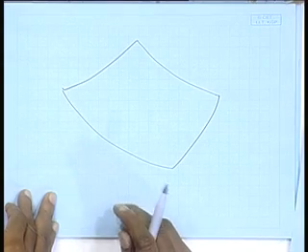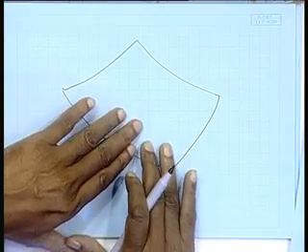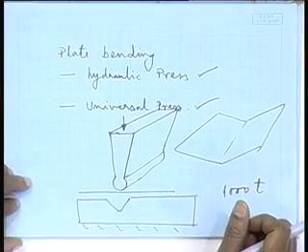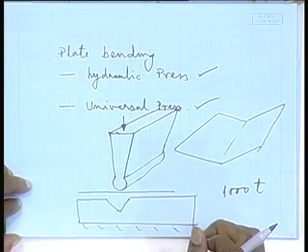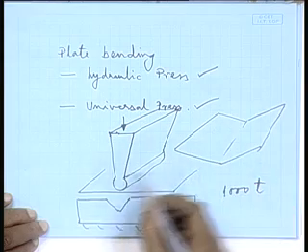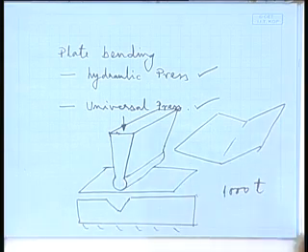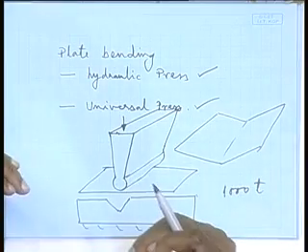As we talked about, from this patch we develop the blank, we have the cut plate, and then you have to put it under this press, and again it is purely a skilled job, depending on the skill of the operator, who has learned probably from precedent, how to place the plate, in what orientation, you have to press the plate and keep bending it in stages.